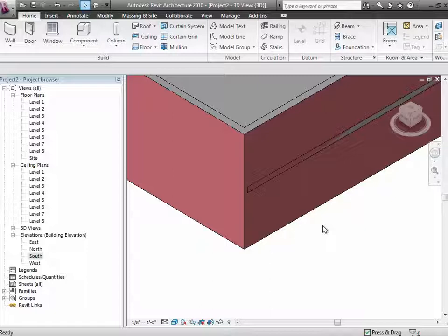Okay? And we don't generally want that, because even in a construction detail, if we had that exterior floor to the wall, we'd have a little gap right here where water could get in, and we'd have a weatherproofing problem. So rather than going through and extending things to the exterior face, it's very rare that you want to extend to the exterior face.